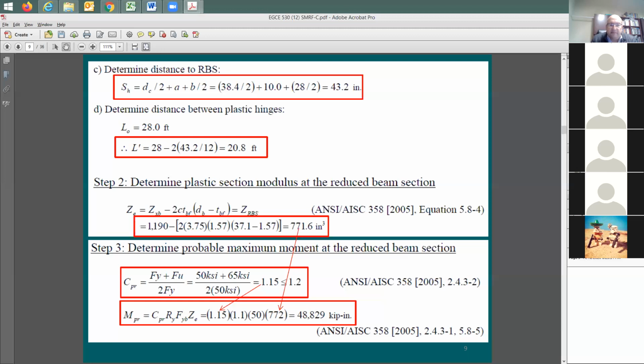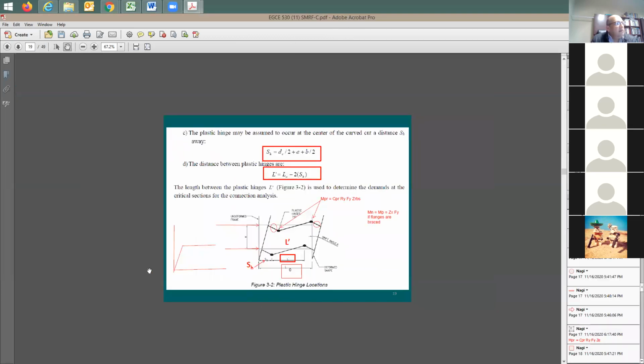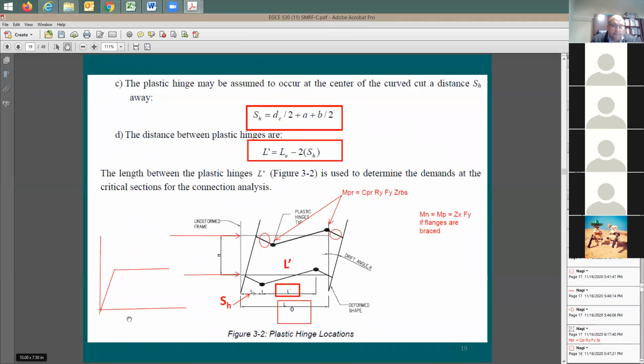What is the mechanism? Is it the critical value for a moment in this case? What do you mean by critical value? That the system or the structure will start to, let's say, bend. At any value, it's going to start to bend? No, but as in a plastic behavior. Yeah. Once it goes into the plastic response or behavior, this is what we're going to call the mechanism.